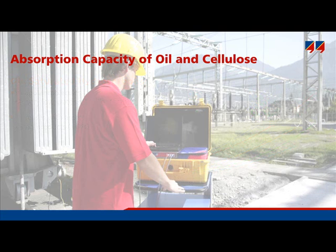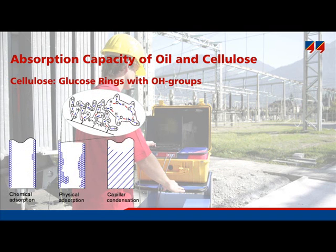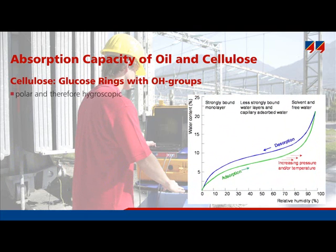In contrast to oil, the cellulose is very different in its molecular structure, since it consists of glucose rings with polar groups. These OH groups are very active in attracting water. Therefore, cellulose or paper can take up a lot of water. The water receptivity of cellulose materials is typically 2,000 times higher than that of oil.